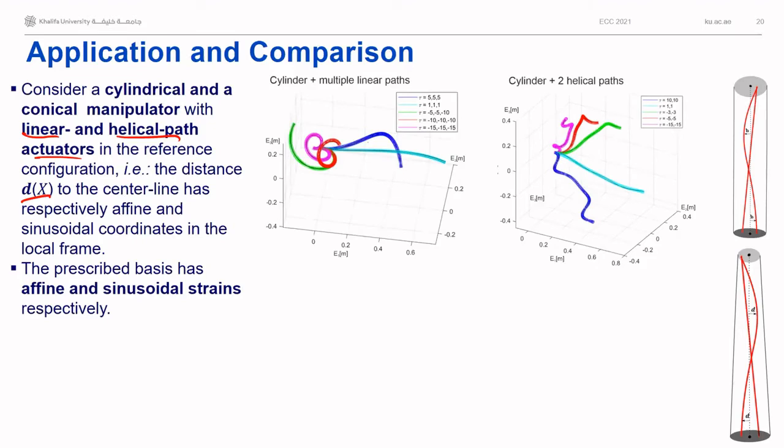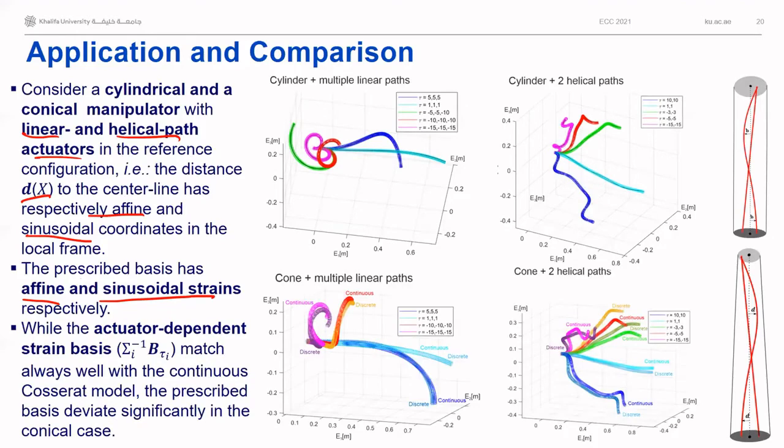In this case, the three models match perfectly, and as the prescribed basis we have used affine and sinusoidal strain bases that resemble the coordinates of the actuator itself.